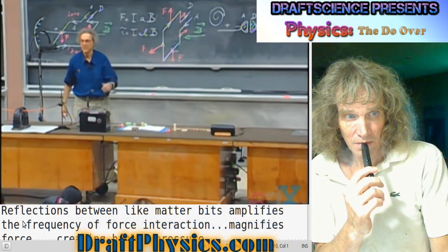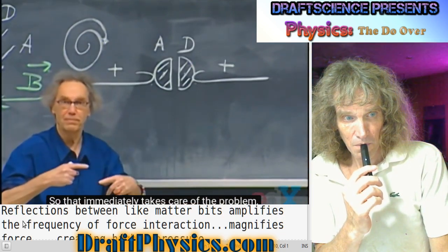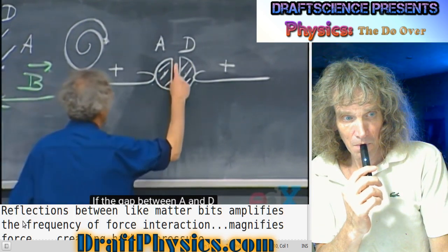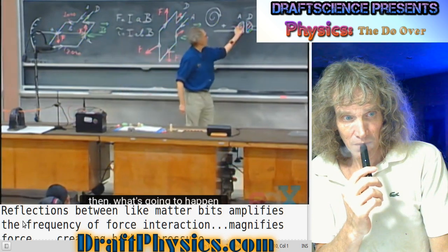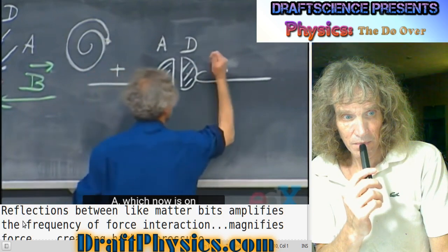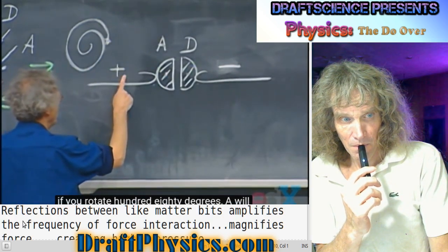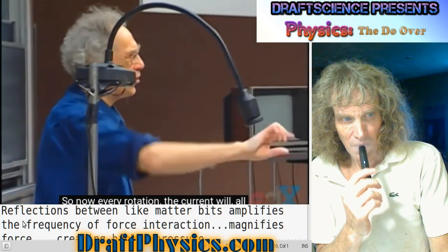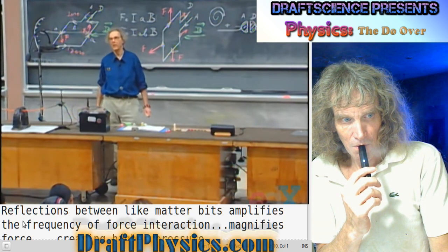In practice, we call them brushes. So that immediately takes care of the problem that the wires wind up. But there's something else which is very clever about this design. If the gap between A and D is an insulator, then what's going to happen when this rotates 180 degrees? A, which now is on the positive side of the battery, this is negative of course, is now on the positive side of the battery. If you rotate 180 degrees, A will be on the negative side of the battery. So now every rotation, the current will all by itself change direction, and we call that a commutator.